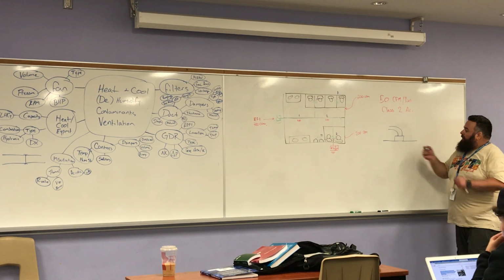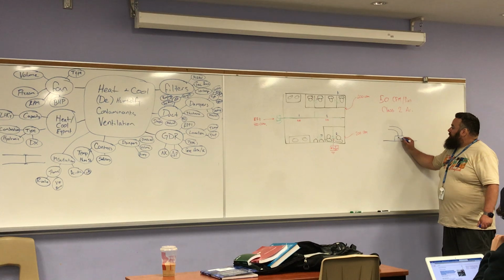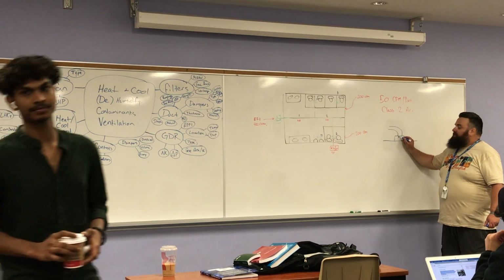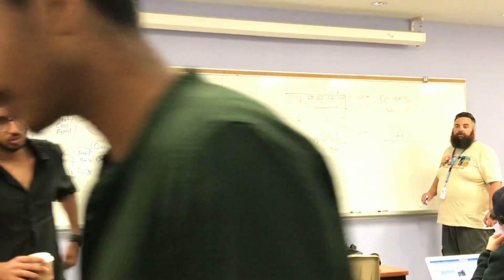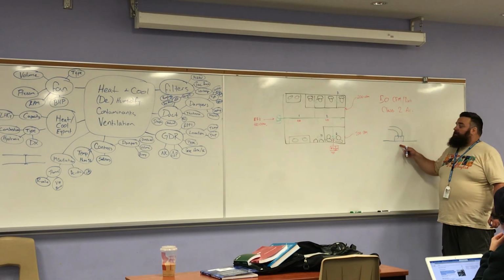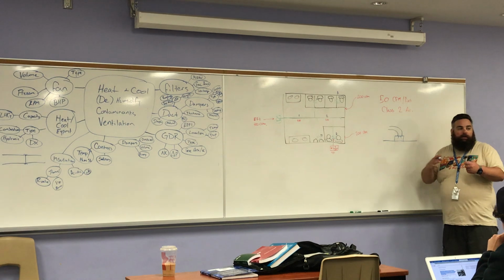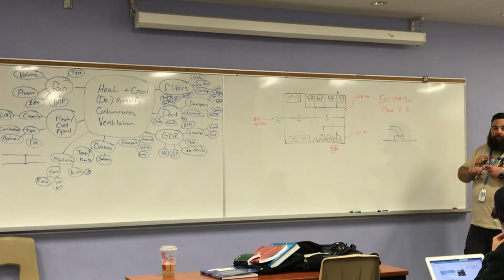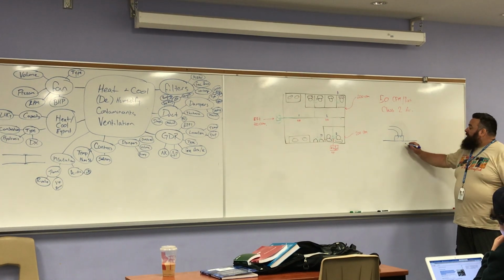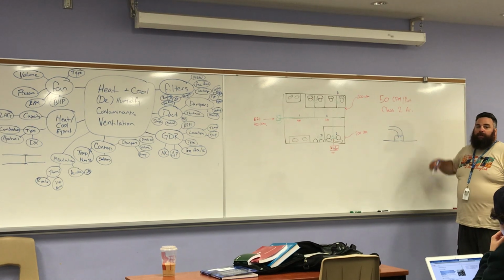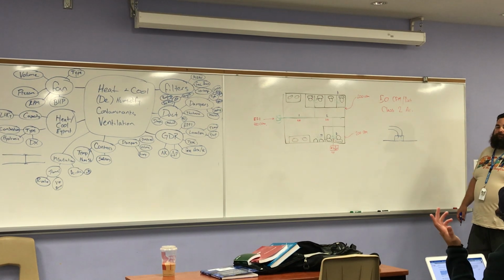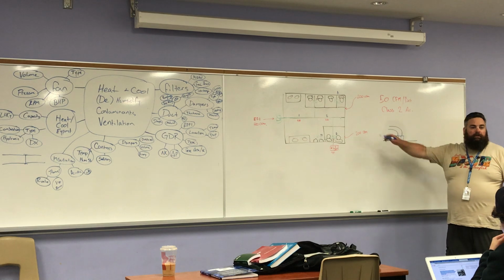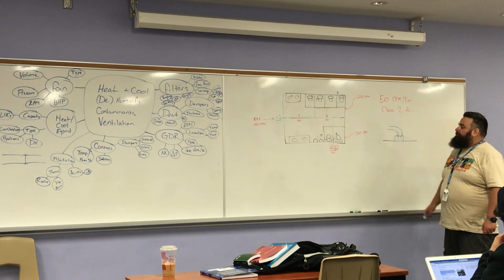all this air has to converge to get into that entrance, doesn't it? That hole is smaller than the egg crate. So we have a convergence there. That has a pressure drop, so I have to account for that pressure drop. What's the next one? The 90, is it? Now the 90. That steals energy as we pass through.